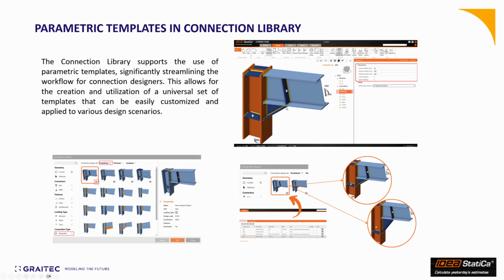For example, if you change the dimensioning of this widener, or web widener, let's say you want to extend it here, the connection will be automatically parameterized and your stiffener will also be automatically adjusted in this scenario. We also have other scenarios that you see here, with screenshots where the stiffeners are automatically adjusted. That is basically what we have for parametric templates. And just to let you know, you can also modify those parameters and add extra parameters to your templates using these tools.